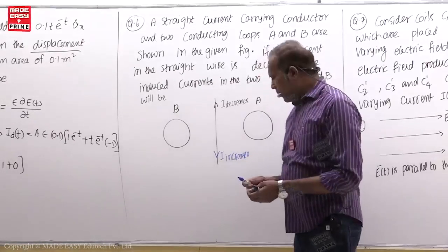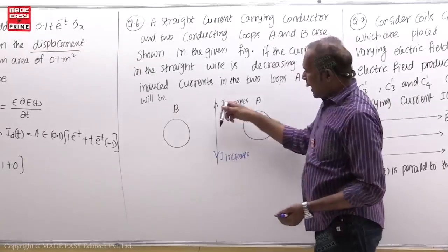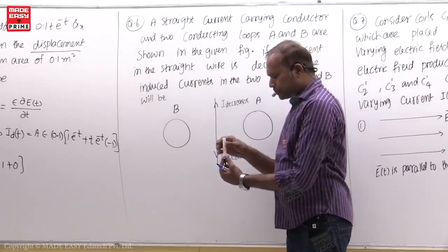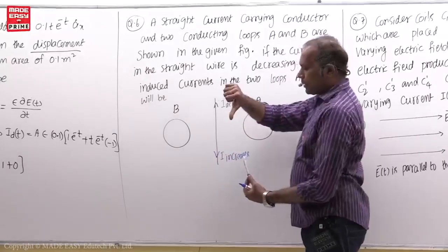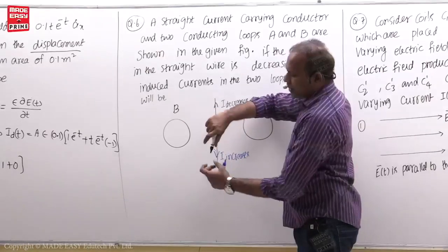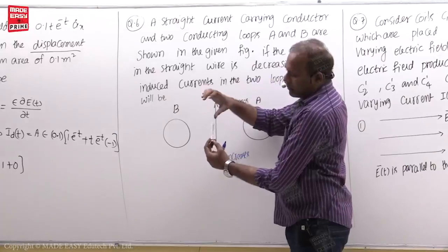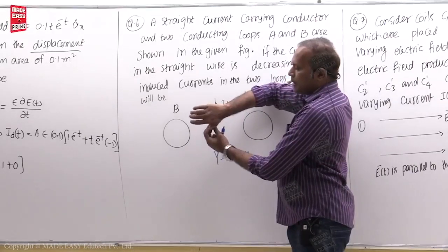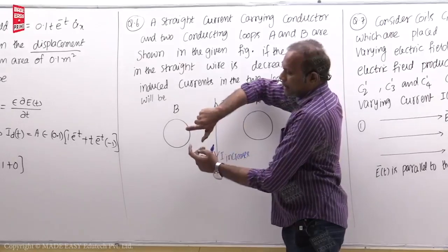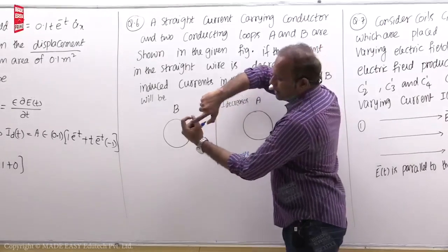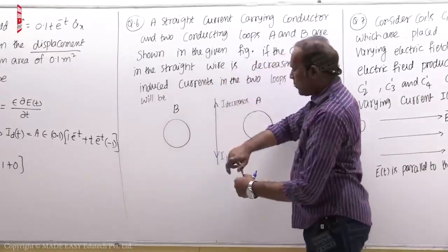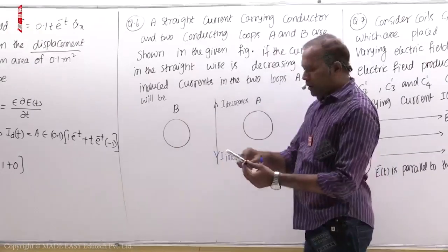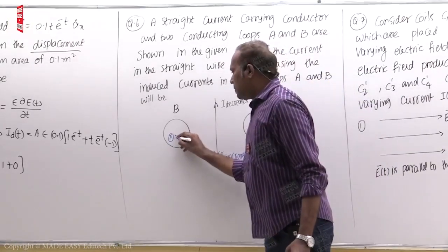Now what right hand thumb rule says, for your convenience, I am getting this conductor here out of the board, and this loop is here like this. Now if I put the thumb in the current increase direction, then here one loop is there like this, and then this thumb is in current increase direction. These closed fingers are in magnetic flux density increase direction. So here this magnetic flux density line is in this closed line direction. So that is entering, this magnetic flux line is entering this loop. Entering means into the board. Into means symbol used is cross. This is B of T.